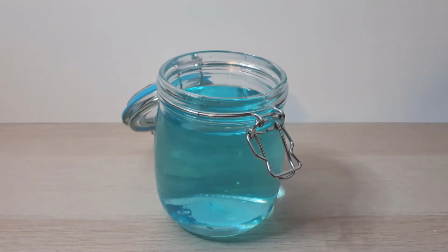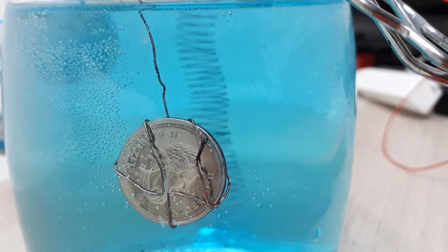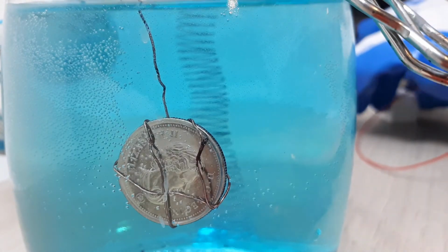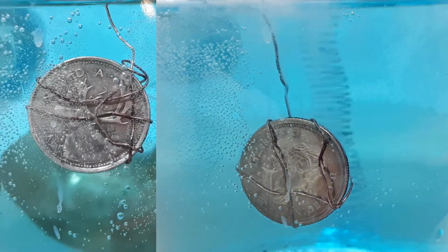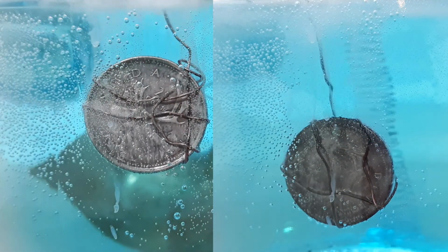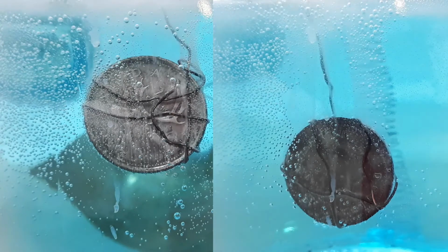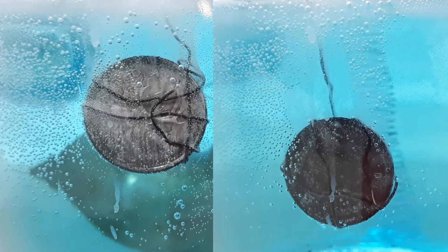When our solution is ready, we can disconnect the power supply. The cathode is retrieved and replaced with the object to be plated, which is then lowered back into the solution, ensuring that the part and the copper anode do not touch. The power supply is then reconnected and left until the desired coating thickness or appearance is attained.